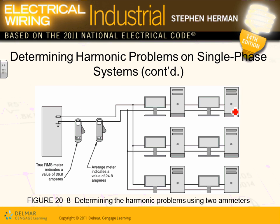Okay. So when determining if you have harmonic problems, here's what you need to do, guys. You take an RMS reading, can you see the RMS value, and measure the current. Look at the current here, 36.8 amps. If you use an average meter, it gives you 24.5. Look at the difference from 36.8 to 24.5. There's a substantial difference. So long story short, they use a method with both an average meter and an RMS meter, and they do a couple of calculations. In a second, you're going to see it.